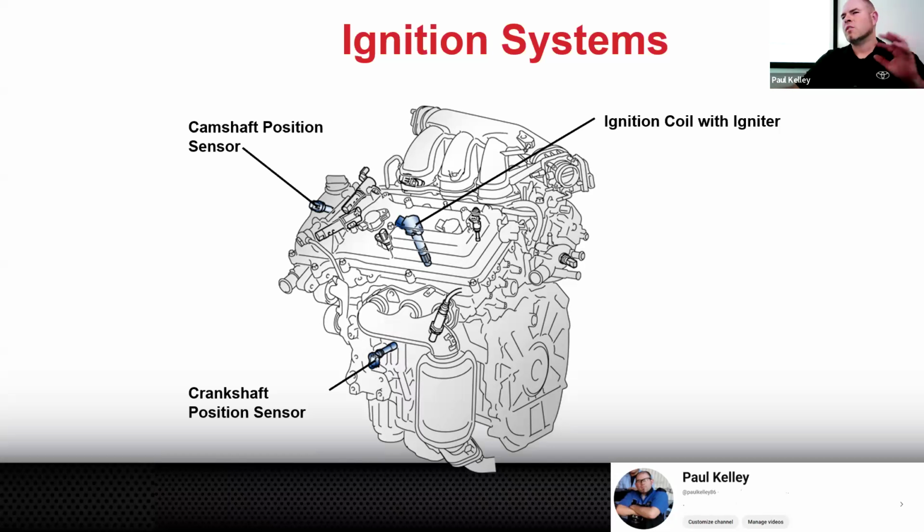From her words, she said he ran a diagnostic, which I'm kind of like, what do you mean he ran a diagnostic? What did he do to diagnose? And she said, yeah, he came over with this machine and ran the diagnostic. And I'm like, all right, it sounds like a code check. Sounds like he just retrieved DTCs, something you've all done now. And then she said yep, and it needed a coil. So he went and got the coil, put the coil in.